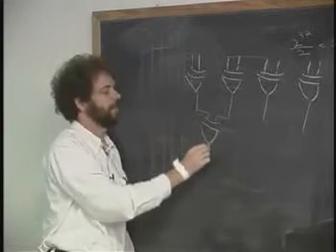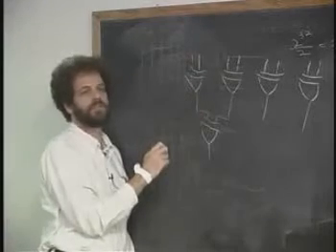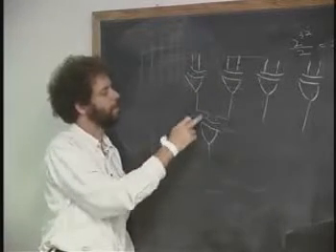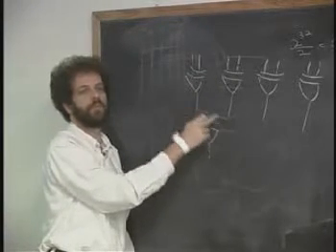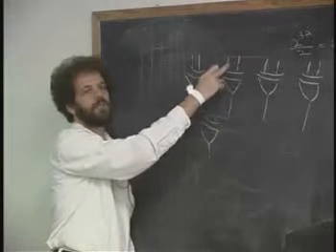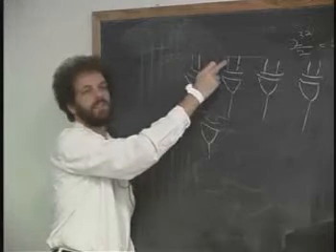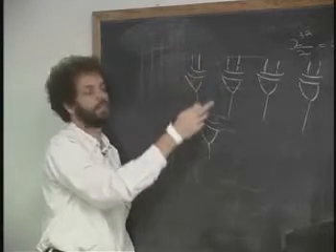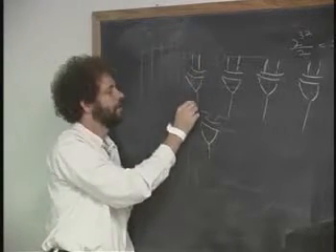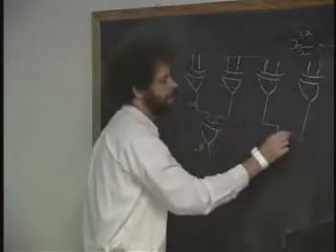Put another XOR gate. And this tells me the parity of 4 things. Because this can be 1 if one or the other of these is 1 but not both. And if one of those is 1, it means that one of these is odd but not both. Right? So either both of these are 1 or none of them. And one of these is 1, so the number is odd. And so this is saying odd. This is saying odd. Of course, I can do the same thing here.